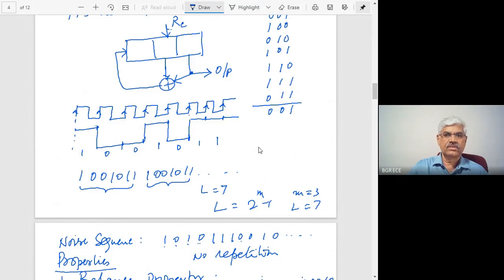So the Earth stations, when they are simultaneously communicating through the satellite, should not interfere with each other. So what they do is, every user will be given a different frequency. If it is FDMA, frequency division multiple access, every user will be given a different frequency band to transmit. They will not interfere.